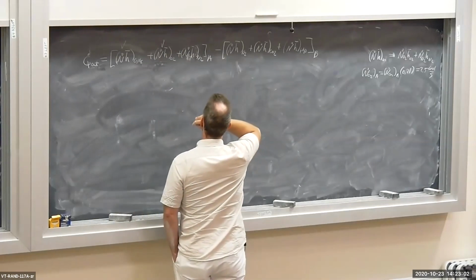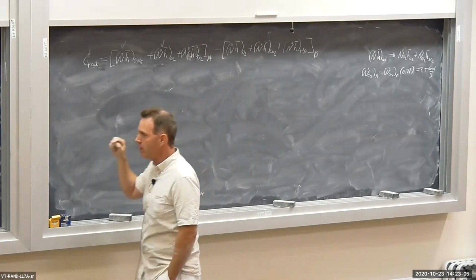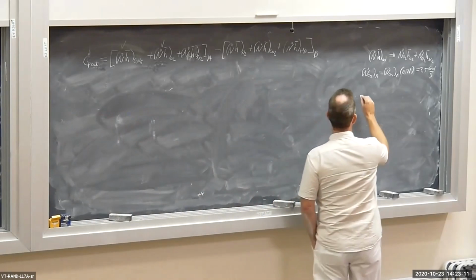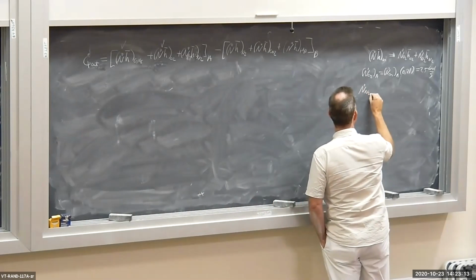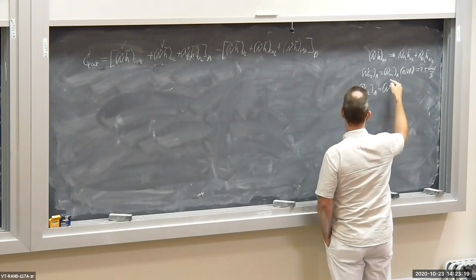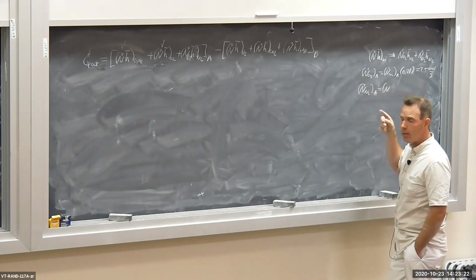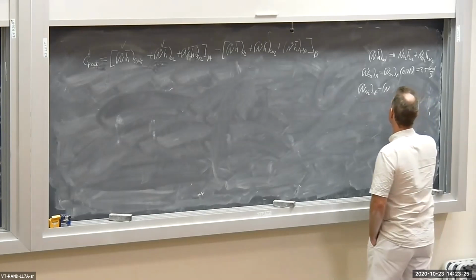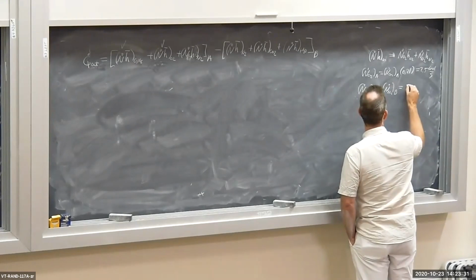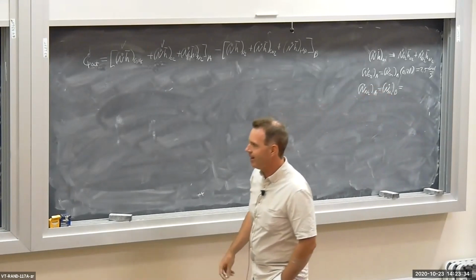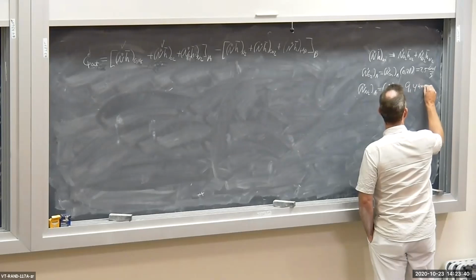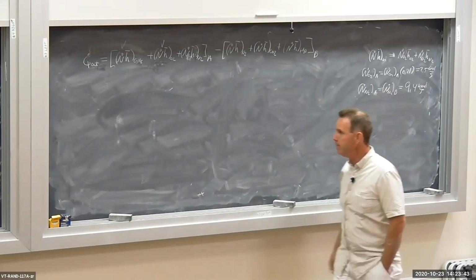I have N dot for the N2. N dot N2 at the inlet is either 79% of N dot air, or you just notice that the nitrogen is not consumed in the reaction. So N dot N2 at the inlet is equal to N dot N2 at the outlet. That means 9.4 kilomoles per second, which is given in our problem statement.